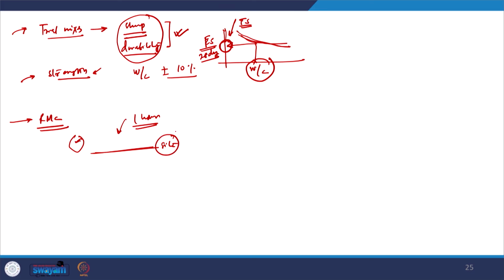In that case, the initial slump which you require here will be a higher slump, okay. And by the time it reaches the site and is being placed, it should be at its design slump. So, in order to increase the slump here, again several measures can be taken, and commonly the value of superplasticizer is adjusted or increased to get the required workability.